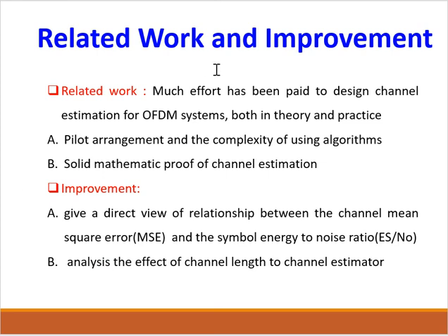Related work and improvement. Though much effort has been paid to design channel estimation for OFDM systems both in theory and practice, such as pilot arrangement, the complexity of algorithms, and solid mathematical proof of channel estimation, what I did is give a direct view of the relationship between the channel mean square error and the symbol energy to noise ratio. I also analyzed the effect of channel length on the channel estimator.